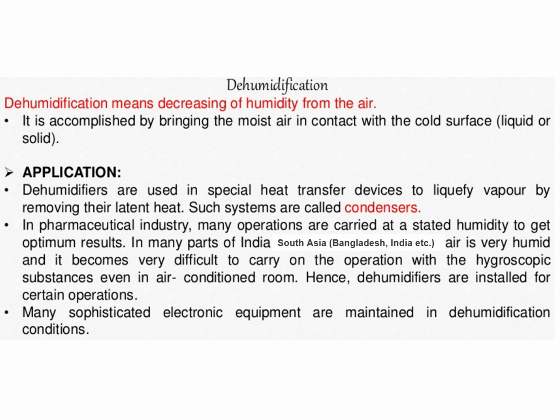Now, the dehumidification, we have already discussed that it is accomplished by bringing the moist air in contact with a cold surface. Actually, this is happening in the cooling coil. In the cooling and dehumidification chapter we have learned this. Dehumidifiers are special heat transfer devices used to liquefy vapor by removing the latent heat. Such systems are called condensers.